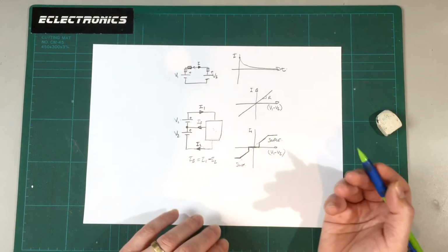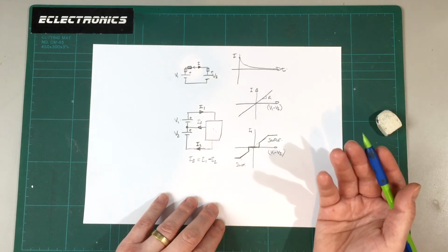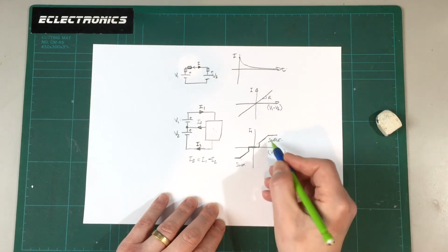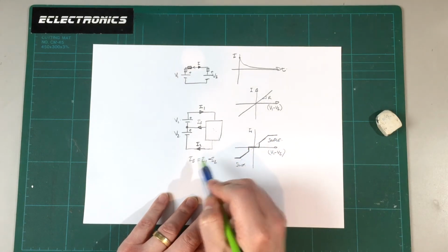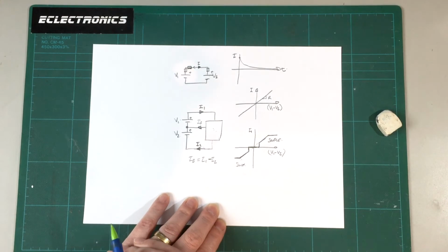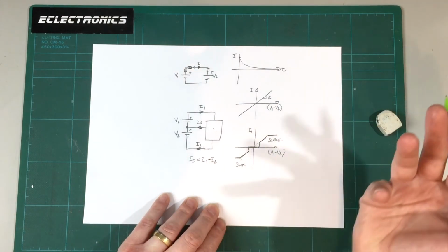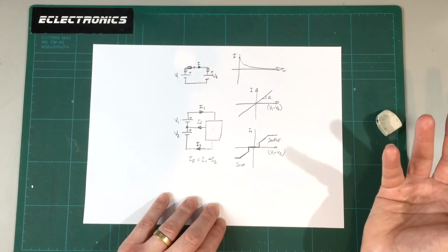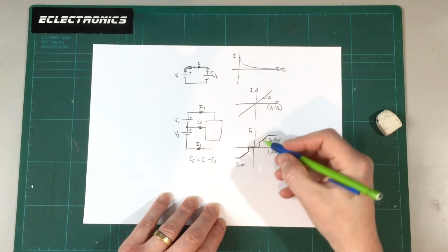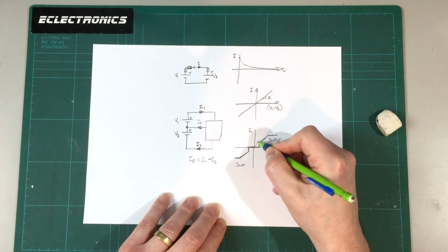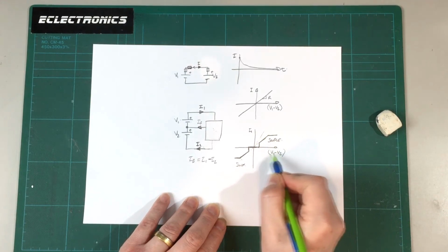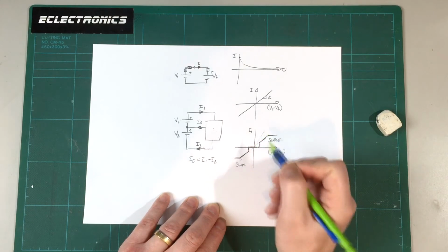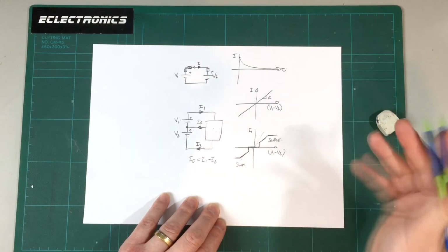They may have a completely different characteristic. So it would be interesting to try and measure this characteristic for the inductive type balancer and then compare that to the capacitive balancer and see how they look. The capacitive balancers seem to have a higher current capability in general, so we may find that this characteristic curve has a higher slope. So for a given voltage differential we get more current, so more strong balancing.